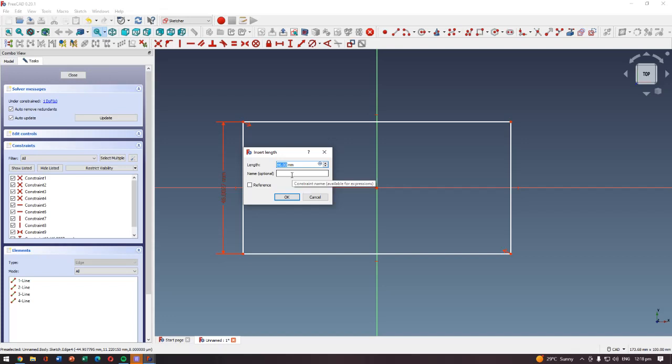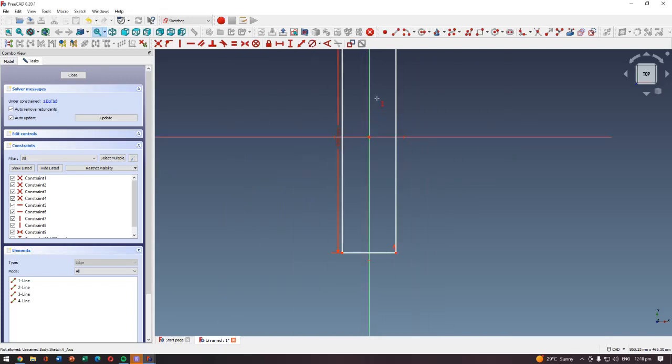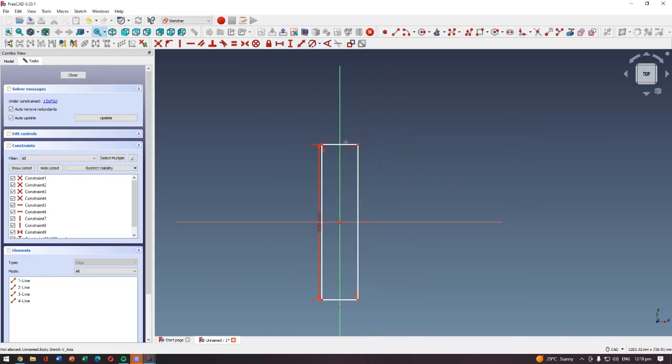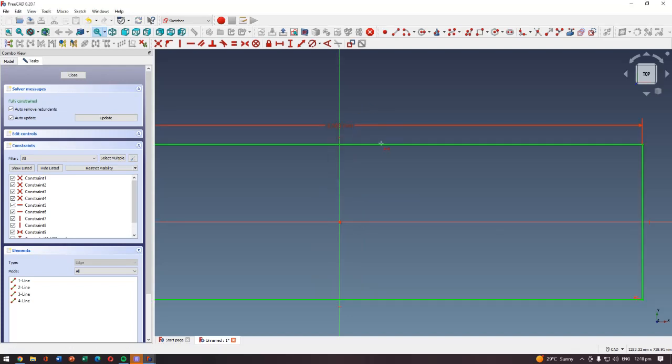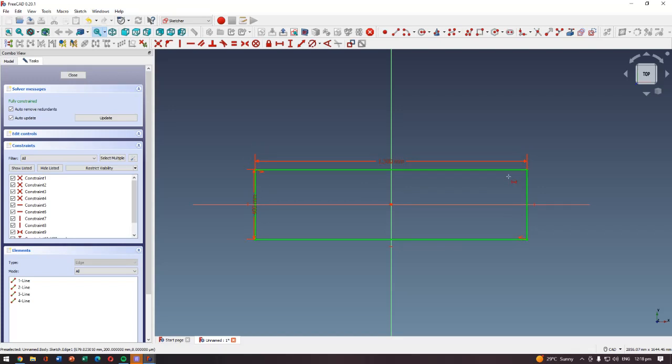So here we can now designate what the length and the width of the duct is. So let's say this is 400. I want this to be the bottom segment of the duct. So let us make it 400. And let's say that the length is around 1500. So this will be our bottom panel in 2D version of our duct.